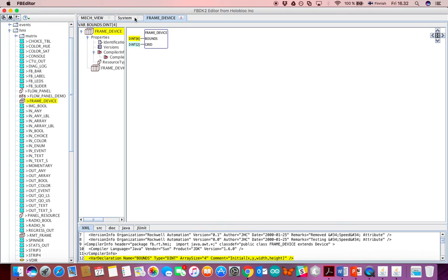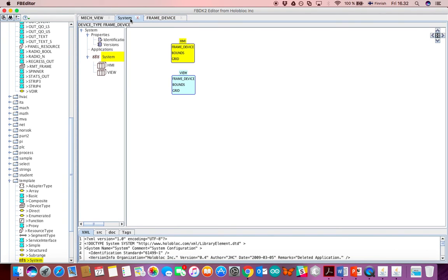Let's use it for a moment, and let's say that we would like our HMI to come here, as I'm showing with my mouse at the moment, in the upper left corner. We can remember that in computer screens the coordinate system starts from the upper left corner, so the 0, 0 coordinate, and the x-axis goes from left to right for this screen, and the y-axis goes from top to bottom, again from this upper left corner initial point for the coordinate system of all the computer screens.